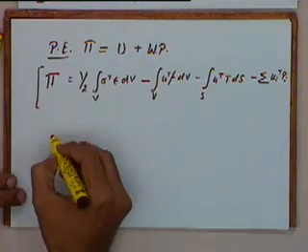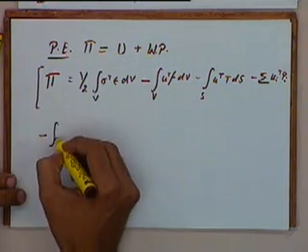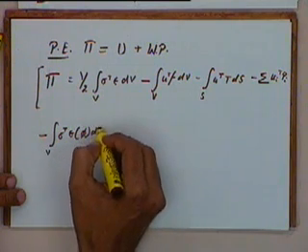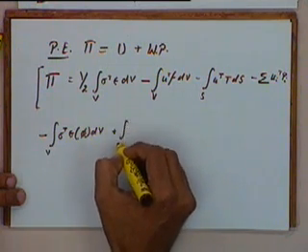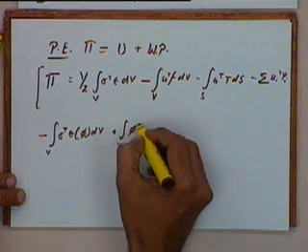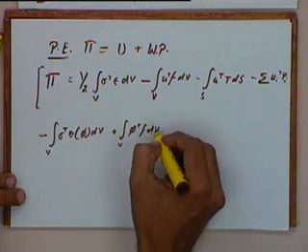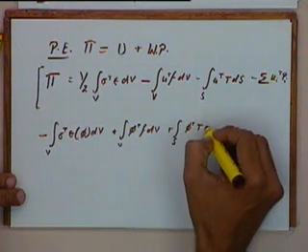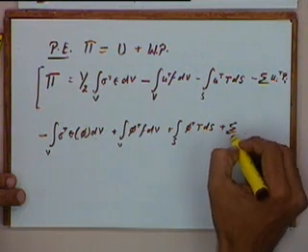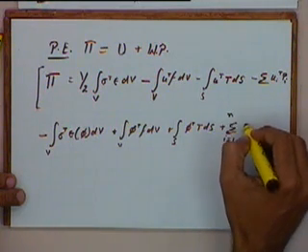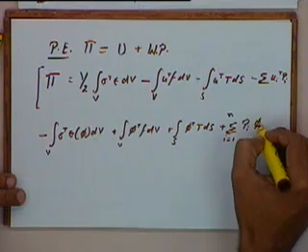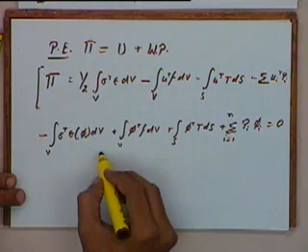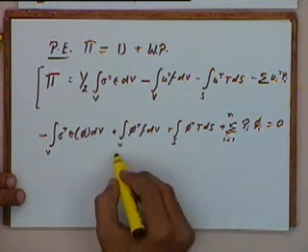And in the Galerkin's approach, we just got minus the volume integral of sigma transpose epsilon of phi dV, plus the volume integral of phi transpose f dV, plus the surface integral of phi transpose t dS, plus sigma i going from 1 to n of Pi phi i, is equal to 0. Okay, this is the internal work done, and this is the external work done.